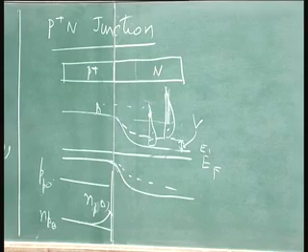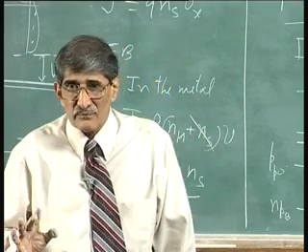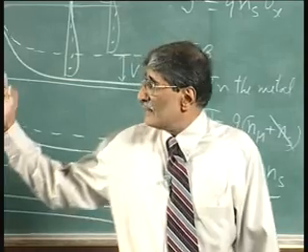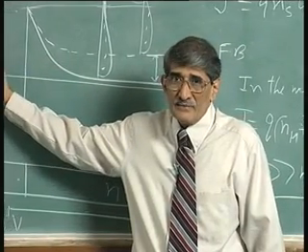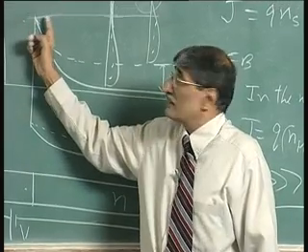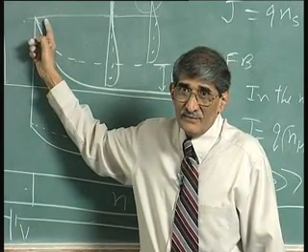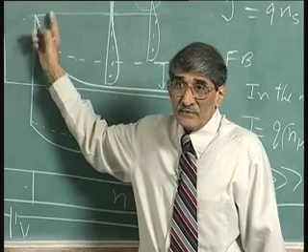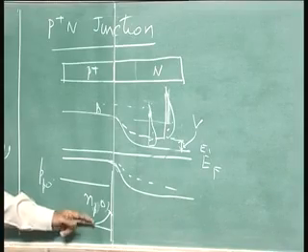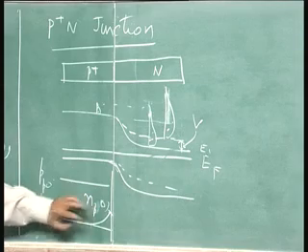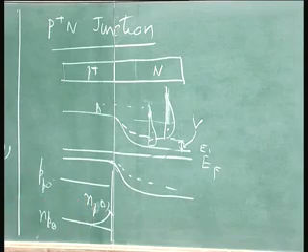So, going back to sum up what I said about these two currents, you take a look at this particular thing. This portion is able to carry the current fast. So, the total current is controlled by how much is coming through this, which is much larger compared to what is being taken away here. This is very small. In both cases, the rate at which it comes up here for the same barrier height will be the same, but the mechanism by which it is taken away in the other region, that controls.